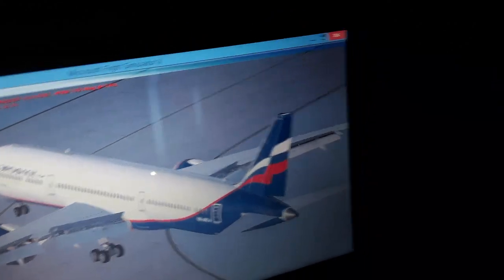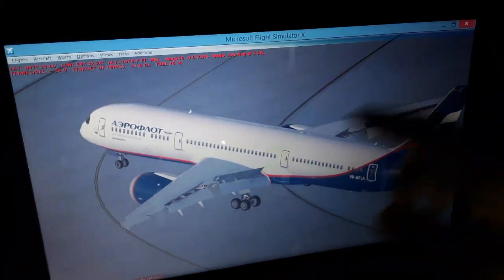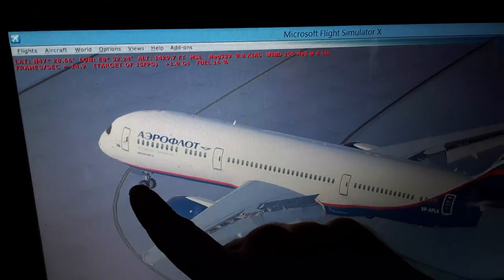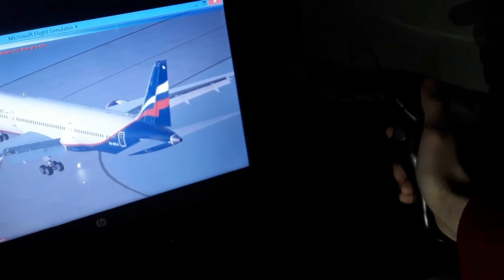And also you can have more rudder as you increase the airspeed. So at 80 nautical miles per hour in takeoff, or in the inverse when we land and you decrease the airspeed, at 80 knots or 140 kilometers an hour, the nose wheel deactivates and there is zero deflection. So we have only the rudder for steering the aircraft in the takeoff above 140 kilometers an hour, or 80 knots, 80 nautical miles per hour.